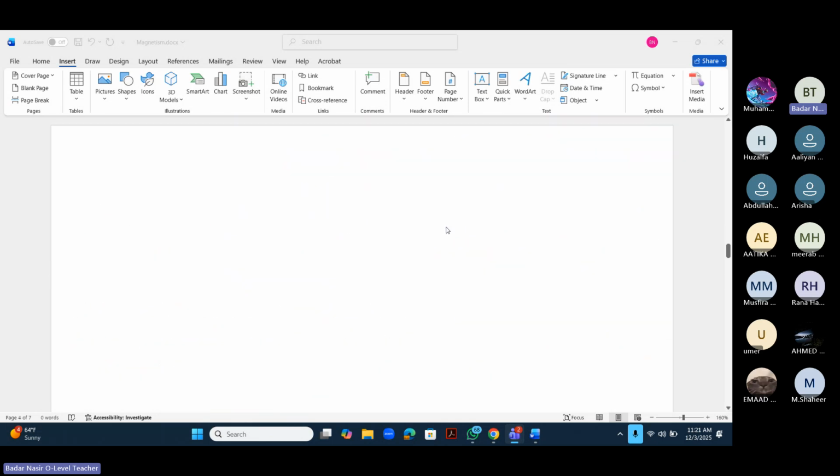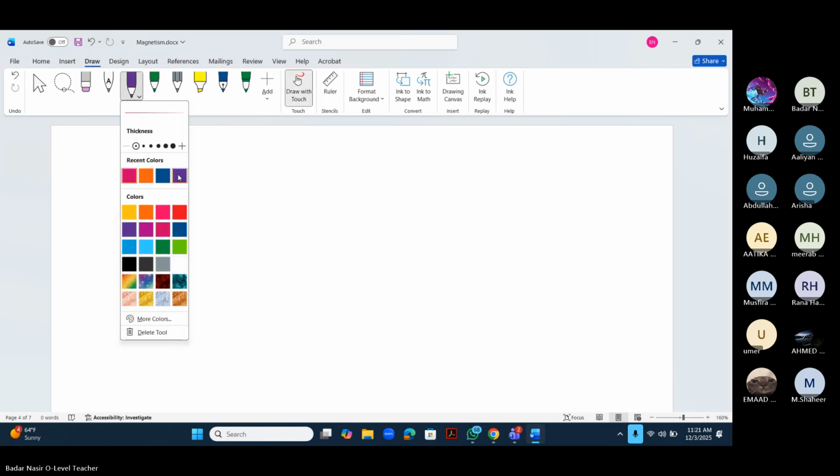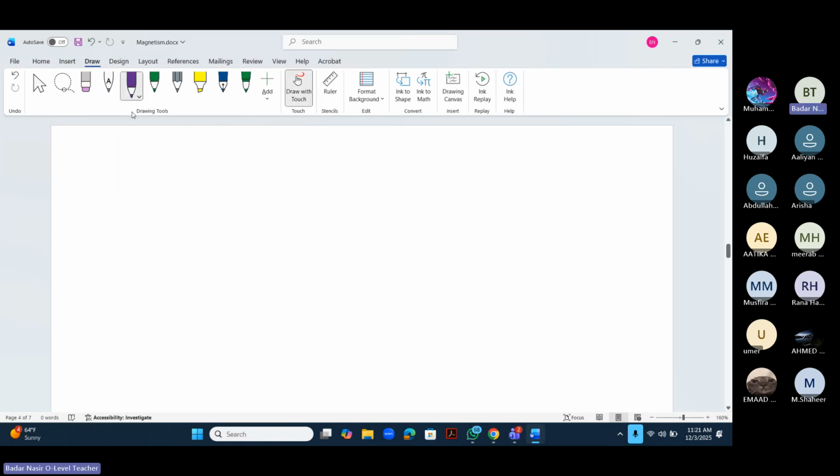Okay, now let's talk about a reed relay. So reed relay has the same function. Okay, so reed relay and magnetic relay, they both are used to control an output circuit which works at high current through an input circuit which works at low current.